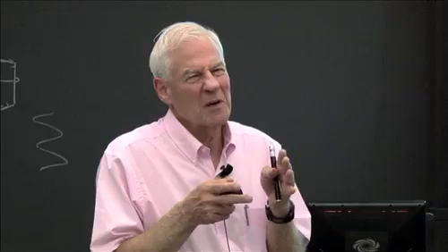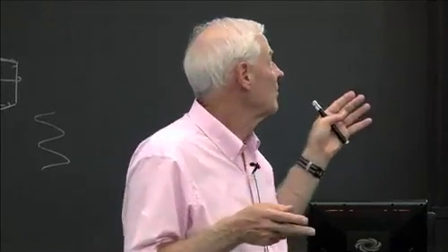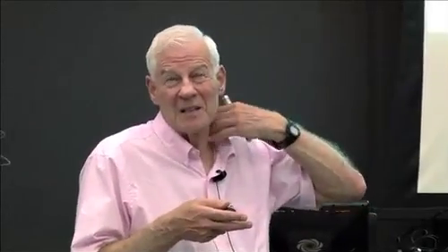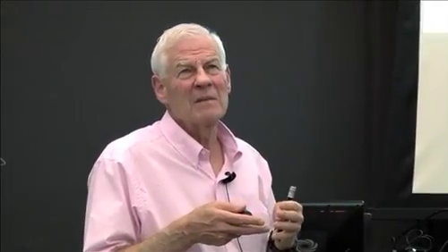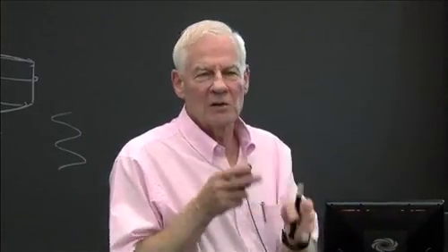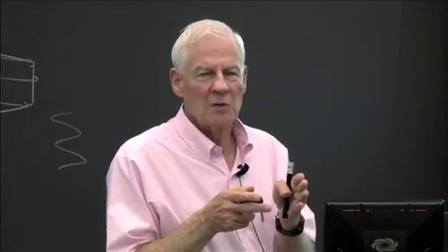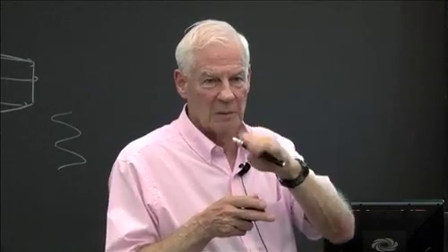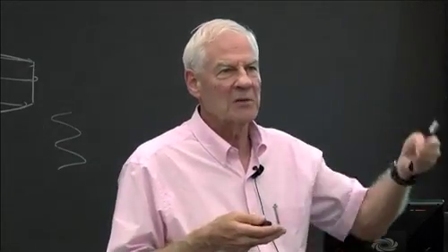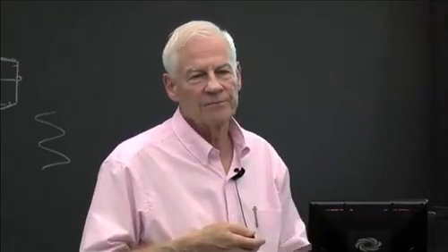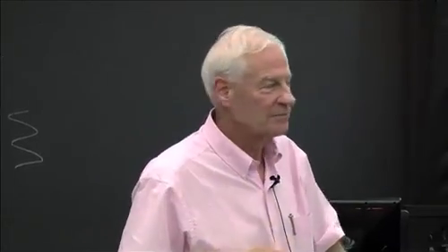So if we only want to work at 25, maybe I'm going to show it next time, I can't remember. We measure temperature at 40 kilohertz, I think, using WMS. So if you're happy with, say, 10 kilohertz, 20 kilohertz, we can use WMS at fixed frequencies to get rid of this window problem. But it just depends on whether it's a laser fluctuation or a window intensity scattering problem, different strategies. But sometimes we park.